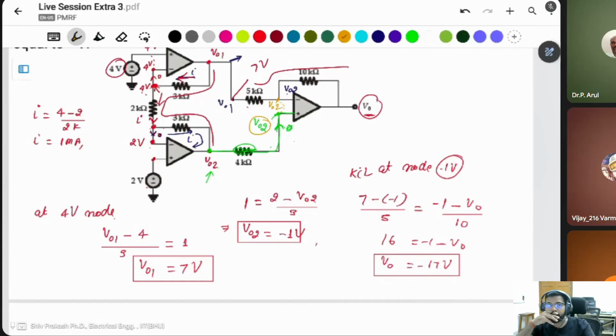You can solve an op-amp question like that by simply using the virtual short and the fact that the input current is 0, then find the circuit path where current is flowing, and then we'll get the answer.